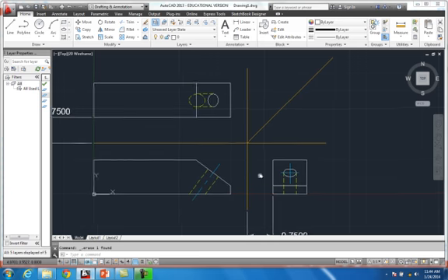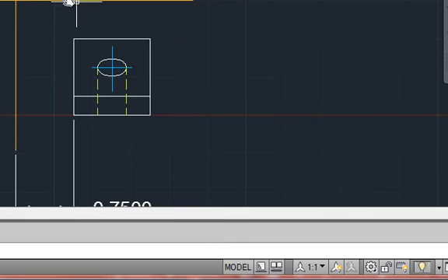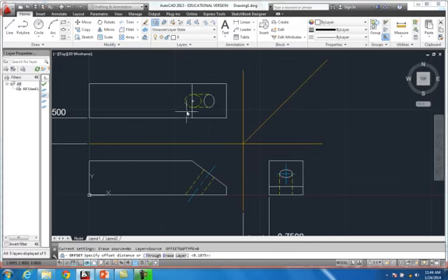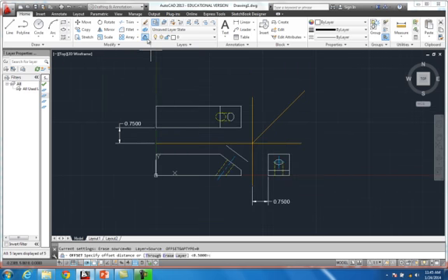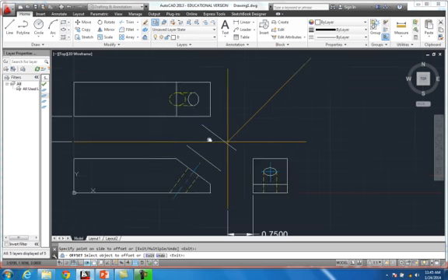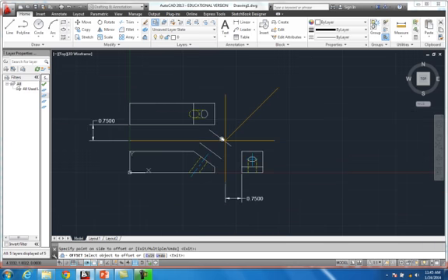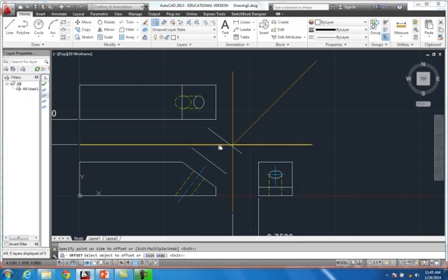Now to do this, what I'm going to do is I'm just going to offset this line right here. Offset it up something like 1/2 of an inch. Something along those lines right there. And again, the distance from my fold plane line is 0.75. I want to hit offset this time at 0.75. Click on that to there. So this is going to be the start right here of my auxiliary line. Now, I should start this one back, and let's do that.